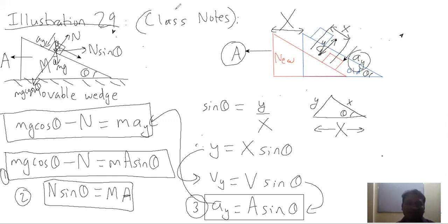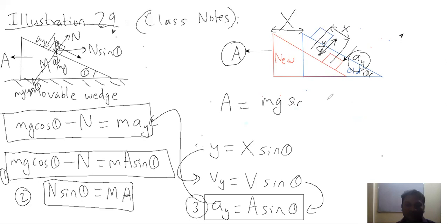On solving, we get the acceleration of the wedge, capital A, as mg sine theta cos theta, the whole upon M plus small m sine square theta. So this is the procedure which we will apply for wedge constraint. Let me show you once again how we will apply wedge constraint. As I said, we have one wedge here.